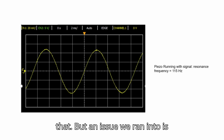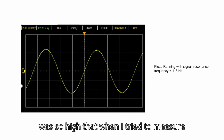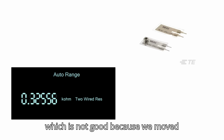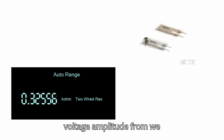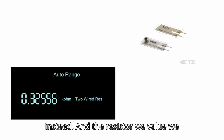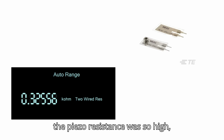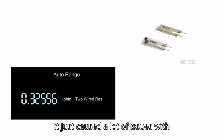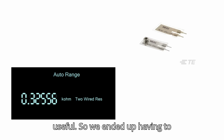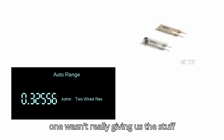But an issue we ran into is that the piezos that we were using had a really high resistance. The resistance was so high that when I tried to measure it, it literally just told me overload, which is not good. So we moved from trying to measure the voltage amplitude on the piezo itself to doing it through a resistor instead. And the resistor value we chose was around 325 ohms, but because the piezo resistance was so high, it caused a lot of issues with measuring it because that resistance was way too high to be useful. So we ended up having to use another piezo that just worked better for us because this one wasn't really giving us what we wanted.